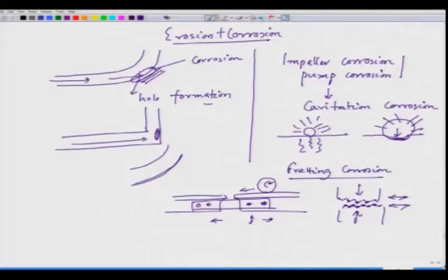So, this is the typical fretting corrosion, and interestingly you might see that from time to time a railway person comes and tightens these fish plates, because the fish plate loosens because of the fretting action. Okay. And here we also have a fear of crevice corrosion, because these also act as a crevice connection. If water falls, water stays there, it remains stagnant, and corrosion takes place.